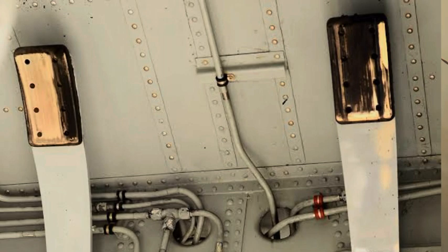Mostly we have some vibrations on the nose landing gear, even though we have a shimmy damper system available to absorb the shimmying of the nose landing gear. But mostly because of high speed turns on the ground, some more stress is brought to one side of the wheel, and that wheel will be a little bit more worn than the opposite wheel, and it will cause some vibrations during the taxi, and this vibration is mostly felt at slow speeds during the taxi, and during takeoff and landing roll as well.